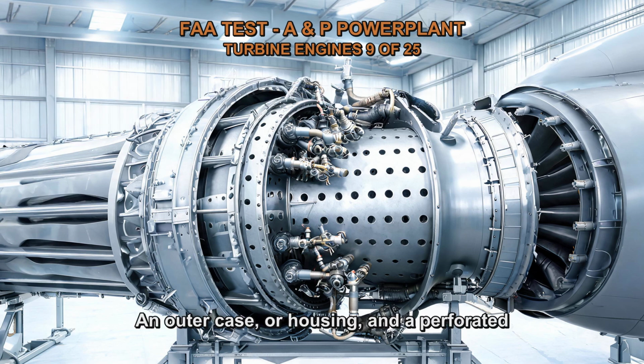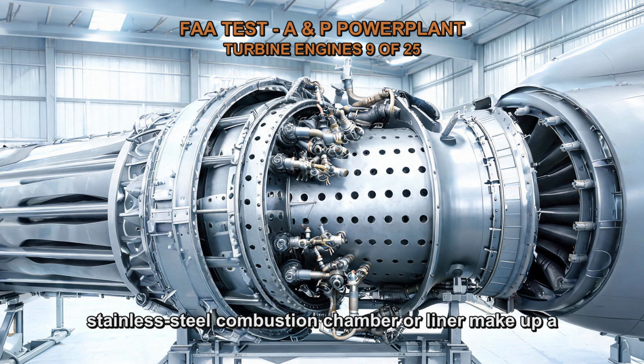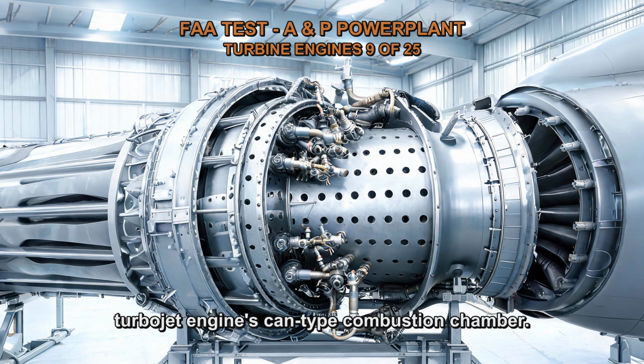An outer case, or housing, and a perforated stainless steel combustion chamber or liner make up a turbojet engine's can-type combustion chamber. For routine maintenance, the case and liner are taken apart.